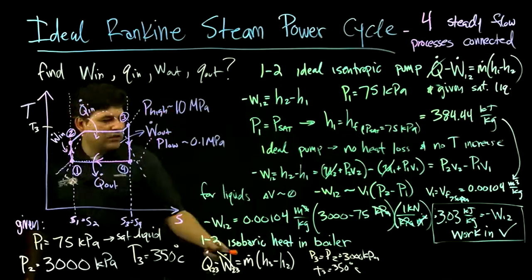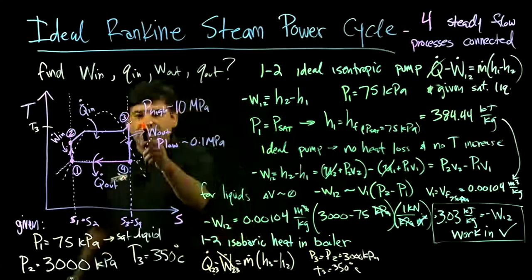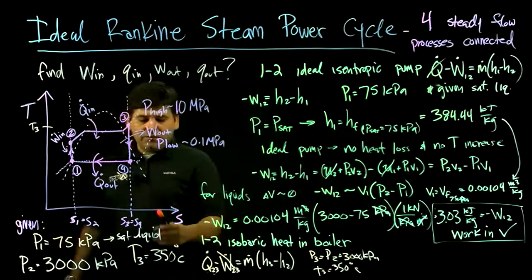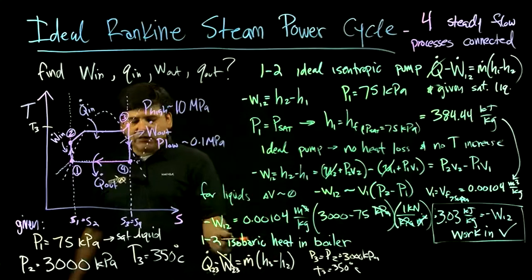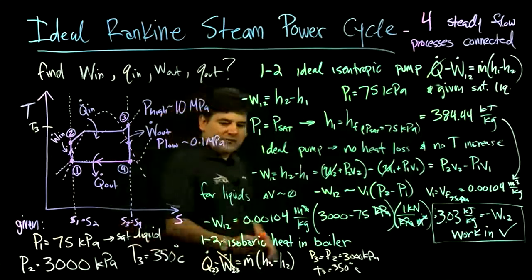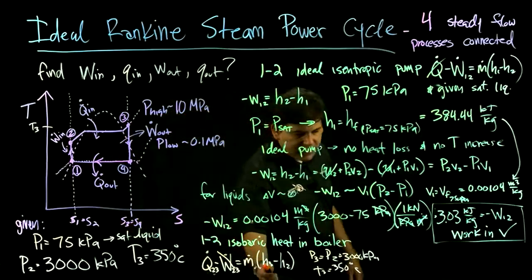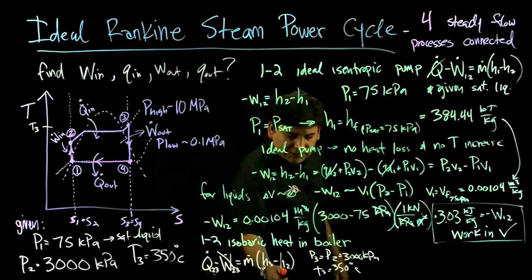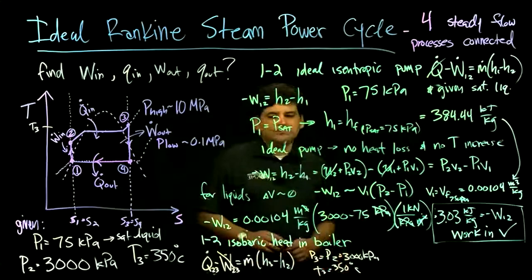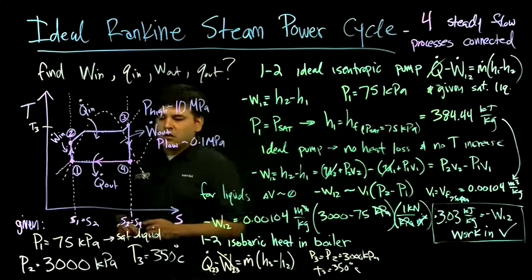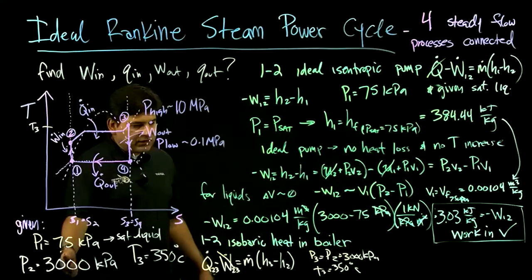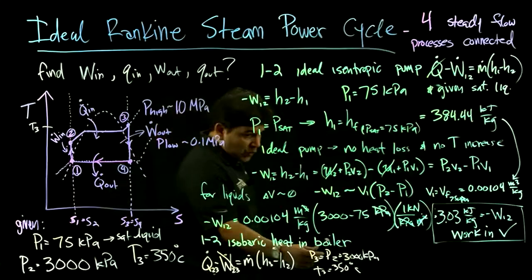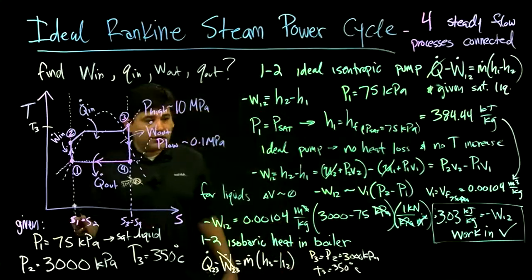So these two are enough to give us H3, in terms of pinning down what table to look for, and then that will give us the H3. So we can find H3. We'll do that next. But the question is, do we know H2? We only know the pressure. We know that it's 3,000 kPa. We do not know the temperature,